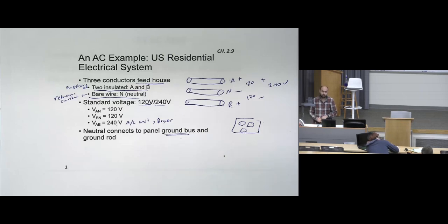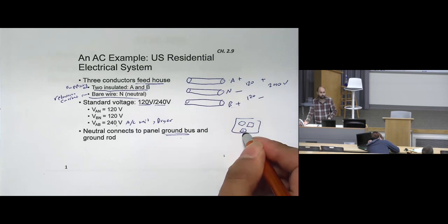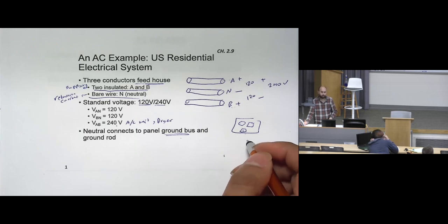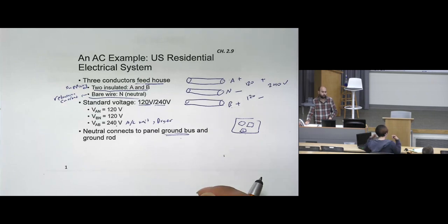This exists in case there is any short circuit or high currents, if something is wrong with your equipment, then the extra or high current will flow to the ground, to the third spot. And there is a protection system, so if any high current flows to this ground, the circuit breaker will trip. So you will not get shocked.